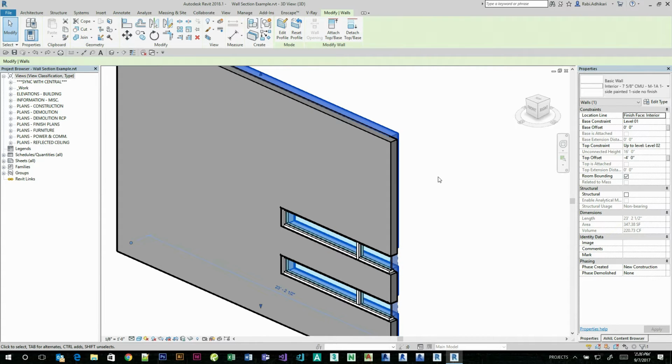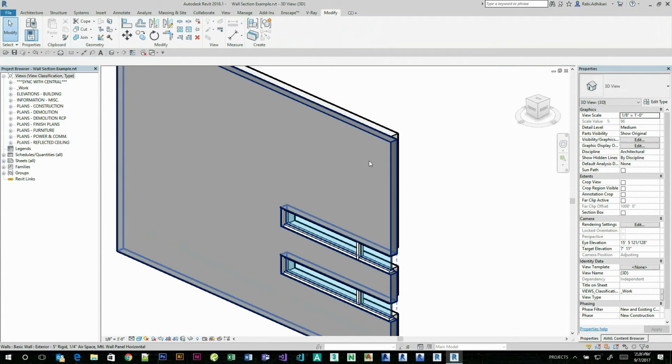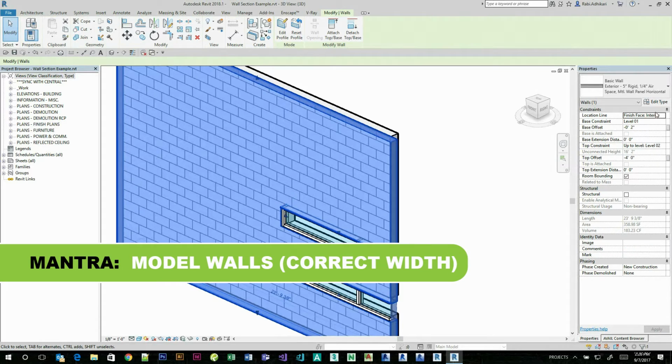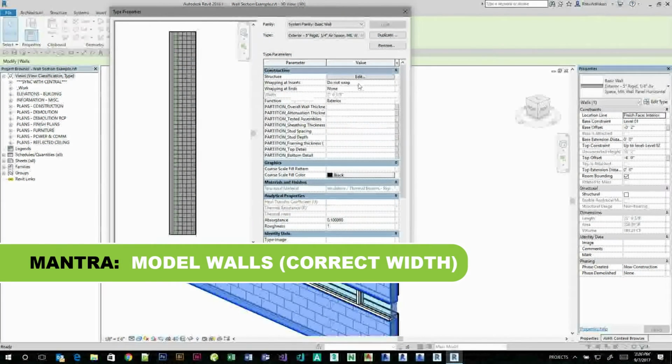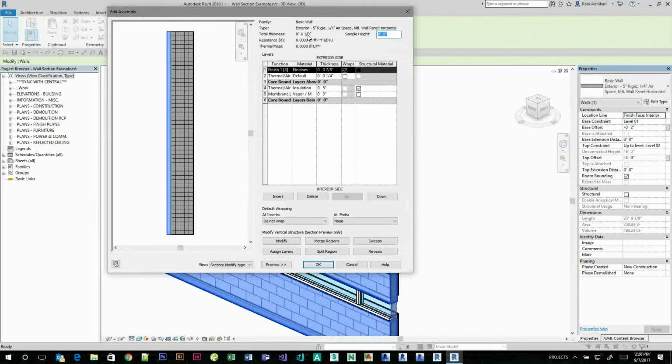And if I were to check the thickness of the metal panel cladding system, then you can see the structure is made out of 6 and 1/8. So you can see there's a thermal layer insulation of 5 inches, some vapor barrier representation, an air gap, and a finish of 7 5/8, which is the actual thickness of the metal panel itself.